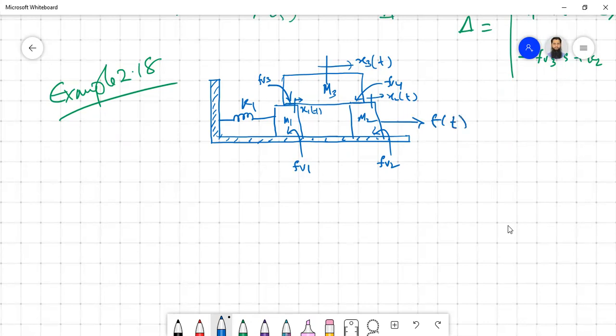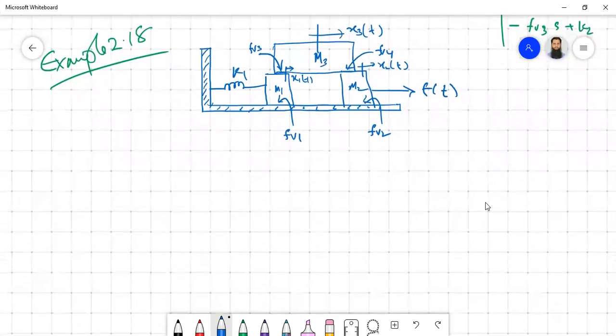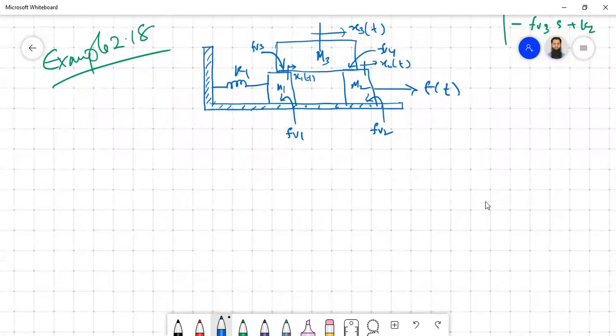So now you have to write the equation for this particular mechanical system. We have three degrees of freedom, or three objects that can move linearly independent of the others. So we actually have to write three equations. From the electrical perspective, we have three loops. So x1, x2, x3 are the three assumed directions of motion.